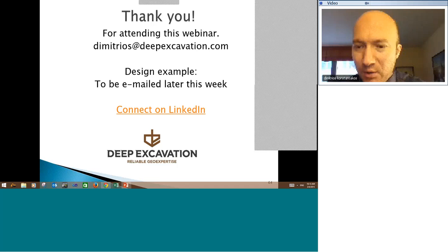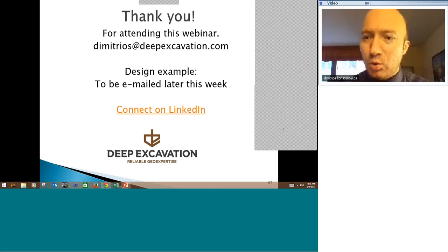There's a question from Christian, if I recommend 3D modeling in finite element methods for deep excavations. It depends. If your model is behaving, I will still do a 2D analysis, but if it is a very narrow deep excavation, perhaps the only way to make it work reasonably is to do some sort of 3D modeling. And not necessarily, you can always back check, so you can come back and do a wedge analysis or a 3D wedge analysis and come back with a Ka factor equivalent and also run your 2D analysis that way. So the answer depends on your problem.